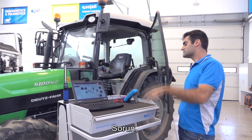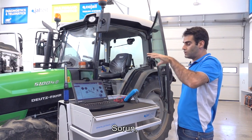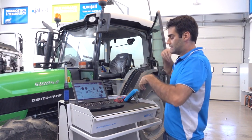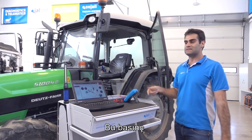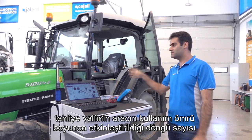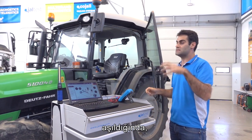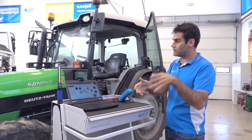The problem comes when the electronic control unit detects that the number of cycles, the number of times that this pressure relief valve has been activated during the lifetime of the vehicle, has been exceeded. It means that the pressure relief valve must be replaced by a new one.